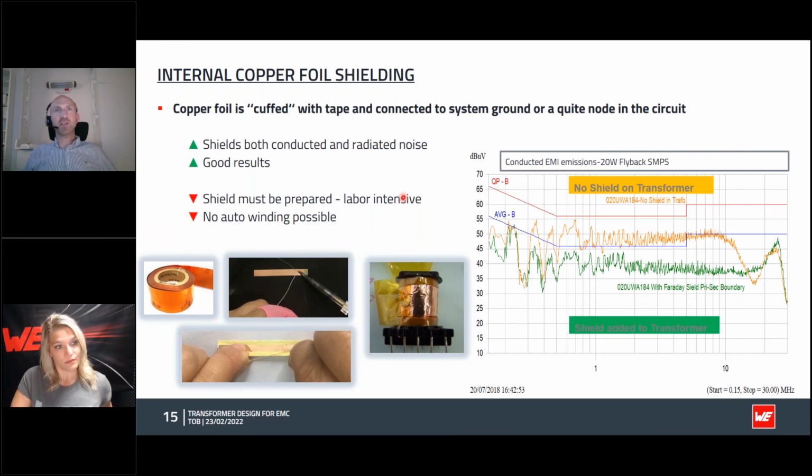Yeah, that's a good question. The core is ceramic, but also it's full of iron, and it is actually quite conductive. If you try to measure, say, the resistance of the core, it's a little bit difficult. But having said that, if you put some copper foil onto a core and pass some AC current through it, then it's actually a very, very good conductor. And so for AC currents, it can really be seen as a conductive part.